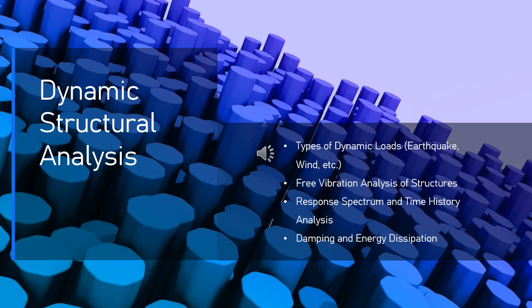Impact load analysis methods. Dynamic amplification. The structural response to impact loads is often amplified due to the high velocity and short duration of the applied load. Engineers must account for this amplification in their analysis. Time history analysis. For complex impact scenarios, like explosions or machinery failures, time history analysis is often used to model the exact response of the structure over time.